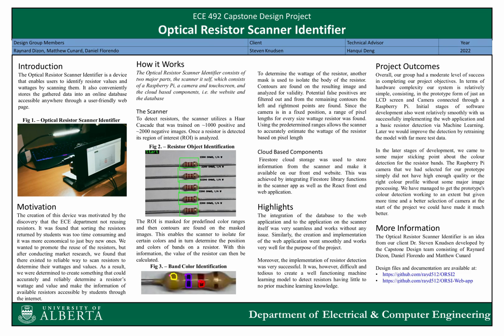We were able to get resistor detection working, integrate the database with the application on the Raspberry Pi, as well as developing, deploying, and integrating the database into our web application. However, we ran into issues where it came to color detection. We chose a camera to reduce the cost as per our client's request, but the camera's image quality was too poor to be able to accurately detect band colors on the resistor. Because of this, we ended up switching cameras to a more expensive, better quality one in order to continue with the development of our color detection algorithm.